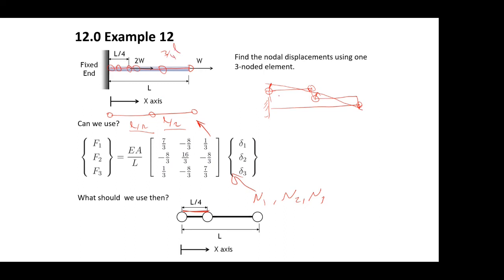So the thing is, if you have the load at probably 1/5 of the length, or if it is at 3/7 of L, I mean, think about how many possibilities you have, and you will find that this is a huge number of possibilities, and you need to rederive the stiffness matrix and the shape functions, and it's a very lengthy process. It will make the finite element method completely worthless.